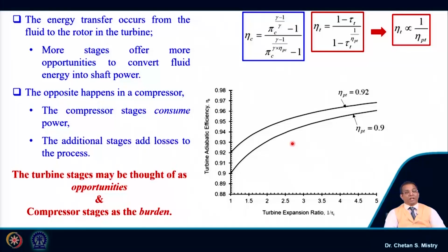favorable pressure gradient. That is what gives us higher per stage expansion, and that is the reason you can just search on the internet, or look at what we are discussing at this moment. If you look at the cut section of an engine, mainly aero engines, you will see more number of compressor stages and fewer turbine stages.